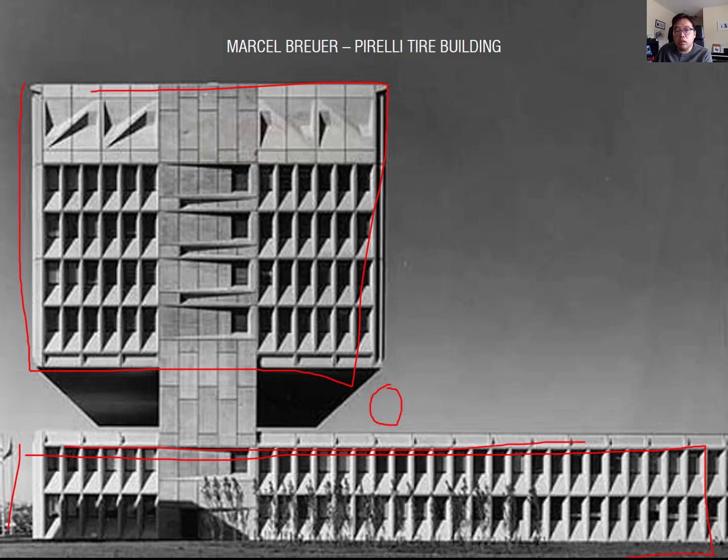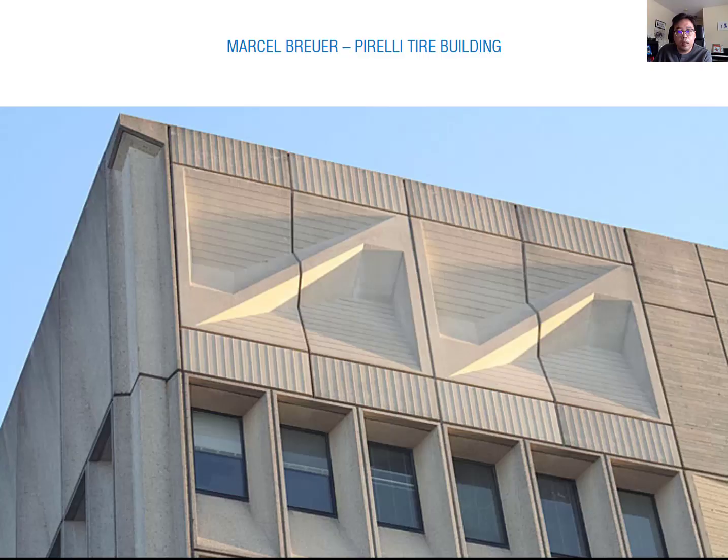I think they're using precast panels to make this brutalist-looking surface. You can see the paneling, and they cleverly use precast concrete, because when you use lots of different form molds for your precast, it takes much more time and costs a lot. So they have to think about using one single precast mold to create different patterns.